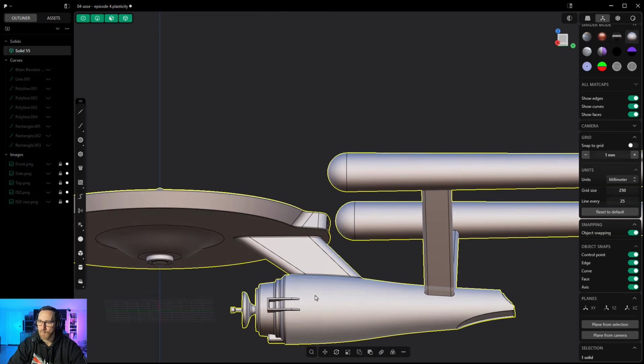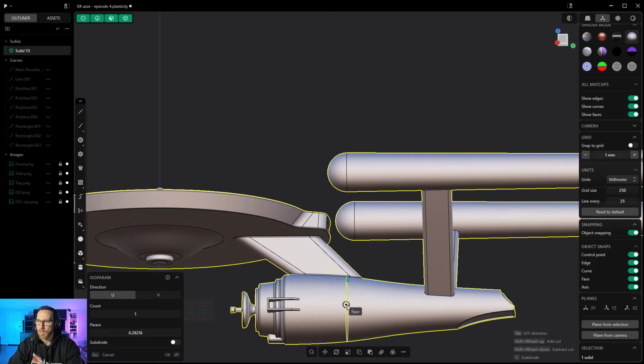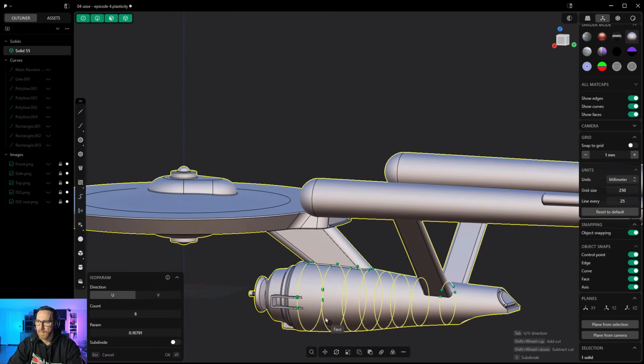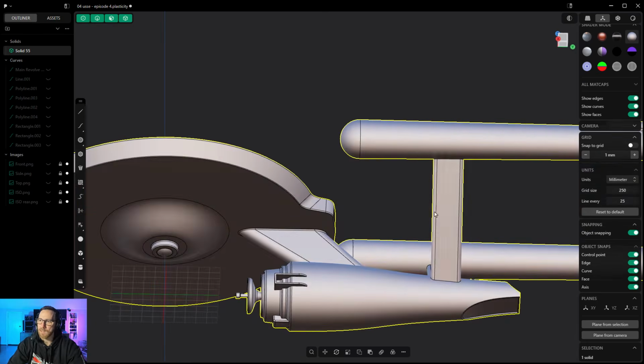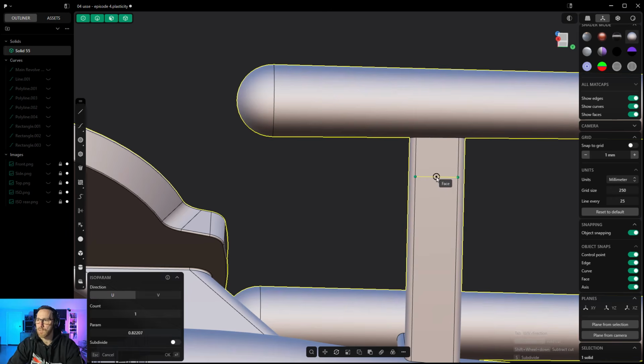And so, for example, if we do it down here, Control and R, you can see that it's dividing it up in this direction. And if I hit Tab, it's creating sort of these vertical streamlines. And it's a great way for us to divide geometry up. And so in the context of, let's say, this face here, if I do Control and R and I hit Tab and hold down Shift and roll the mouse wheel, you can see that I'm able to basically divide this up vertically.